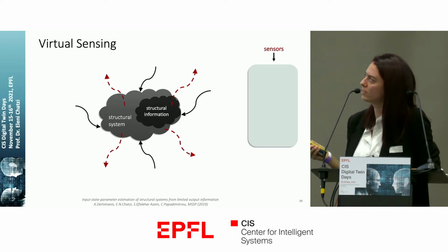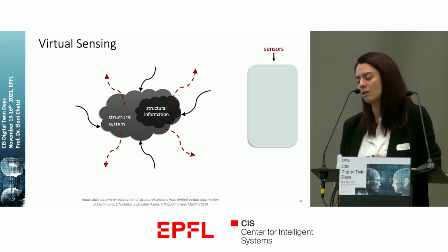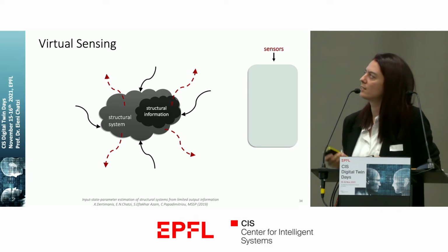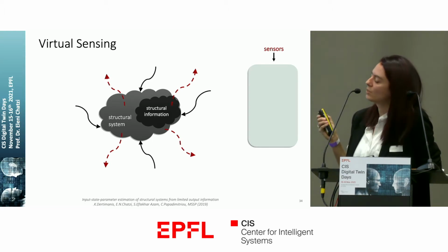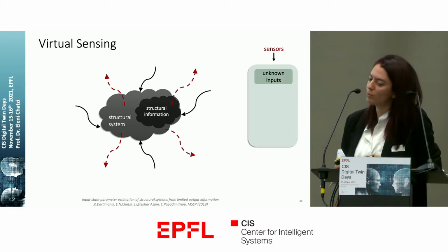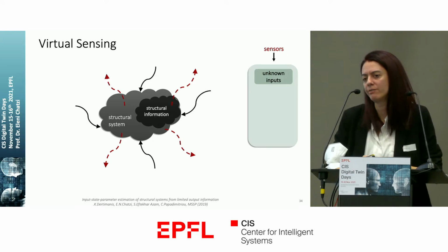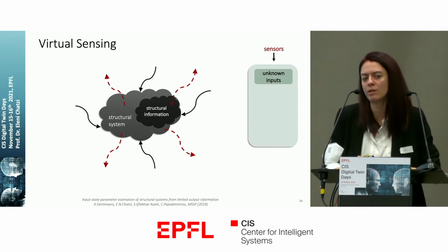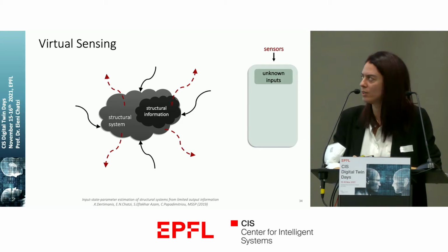So imagine you have a structural system, and as I said before, you have some sort of information, could be sparse, could be incomplete and noisy, that come from different sensors that are deployed on this system. And so the goal is to extract or use this recorded data, even though you might have inputs, meaning loads, that are not necessarily known. Unfortunately for us, in most cases, we do not know the loads that are acting on our systems. We cannot exactly and precisely measure these.